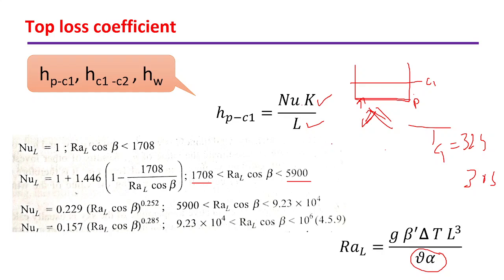For this equation you have to take an average. 70 degrees centigrade plus 273, what will it be? It will be 343. Correct? Yes, sir. The temperature of the absorber plate is given as 70 degrees centigrade, and for C1 we have assumed 325.